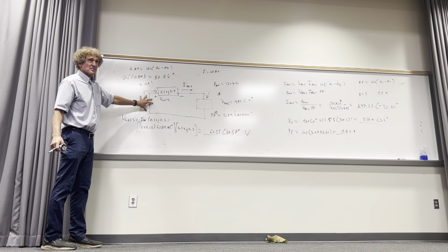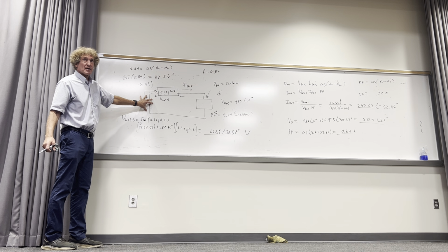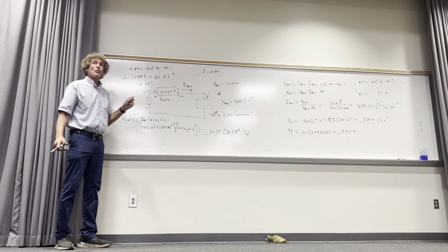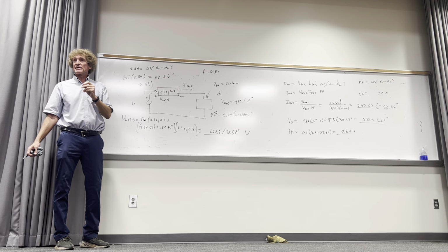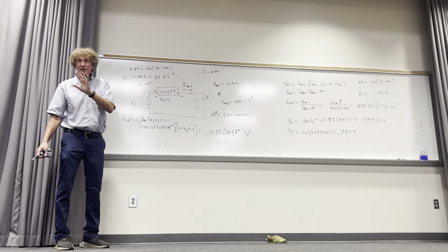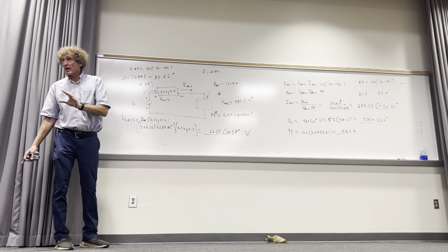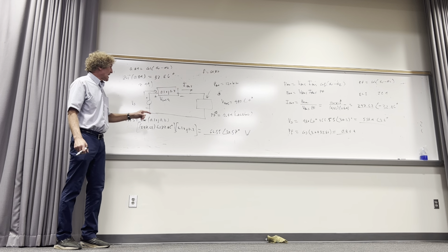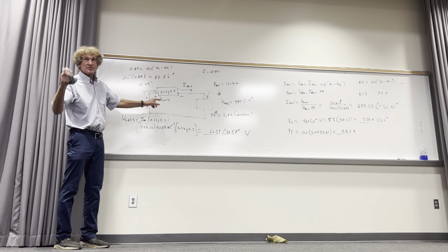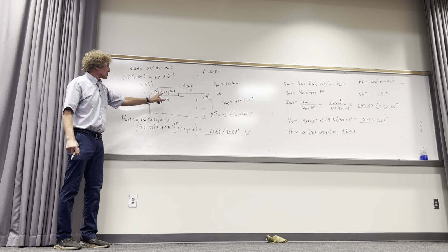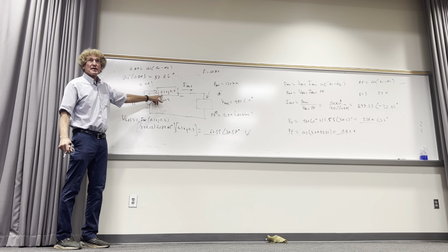What else is responsible for dissipating power that's supplied by the power company? Anyone? You guys see it? Yes, sir. The 0.1. That's right. Now, if you want the total power, you would take, and now you don't need the 1/2 now. These are RMS currents and voltages. Now you take IRMS squared and multiply it by the resistance, 0.1.